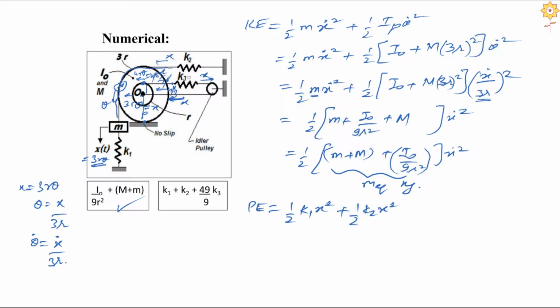So total amount of deformation for this spring is how much? x over here, and over here it is 4 upon 3x on this side. So total amount of deformation is x minus of minus 4x upon 3, that is x plus 4x upon 3. So 1 plus 4 upon 3, times x. So deformation is how much here? 7 by 3x, right? So I want the contribution from the spring of stiffness K3, it should be half times stiffness K3 and 7 by 3 x squared of this.